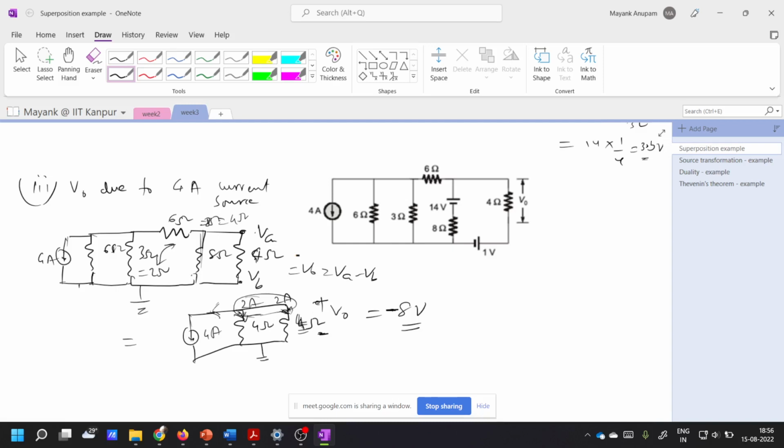Correct. So basically, I understood. You see this 4 ampere is flowing like this, right? So in this branch the current is like this. Here I showed the current like this. Am I showing it correctly or wrong? There is something wrong here. Yes, it is wrong, because you see the current is being pulled out of this branch here. So the current here should go up like this. It should not flow down. Now can you tell me what is the voltage V, VA minus VB?